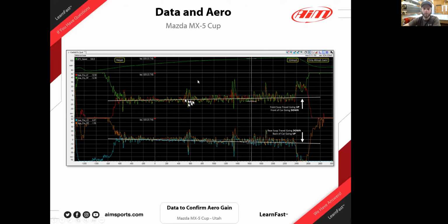Gotcha. Yep. And just so you know, the front end of these cars is a normal front bumper. These are 100% stock, but there is a piece of plastic that goes back to about behind the engine that is 100% a flat bottom, from the face of the front bumper back to about the suspension, maybe a little behind the engine. So there is a bit of a flat bottom tray there that is probably creating this.